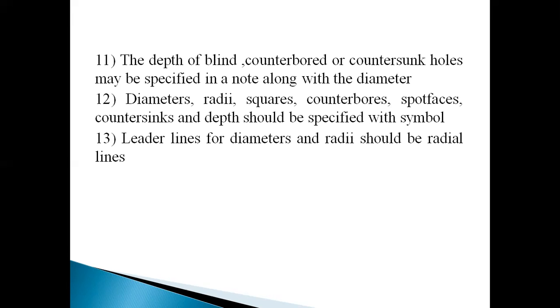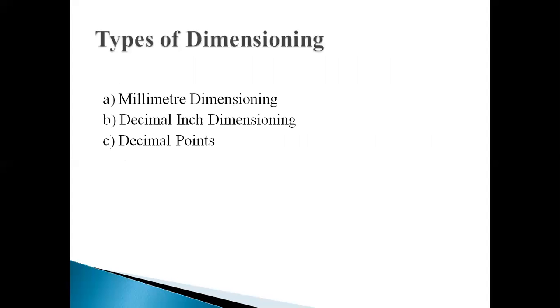It should be used properly and shown in true profile views and refer to visible outlines. A zero basic dimension applies where axes, center planes, or surfaces are shown coincident on a drawing.